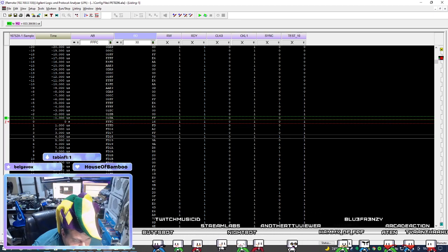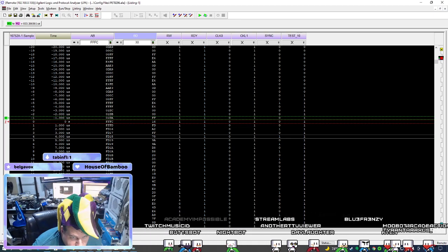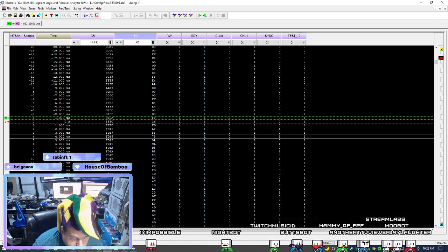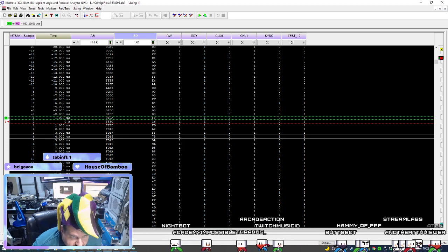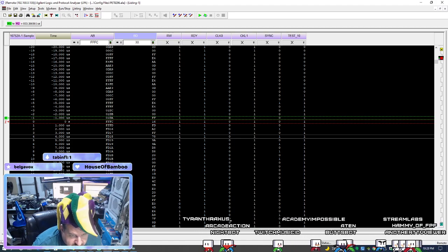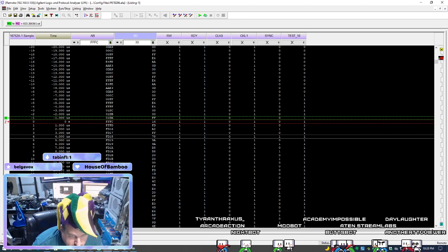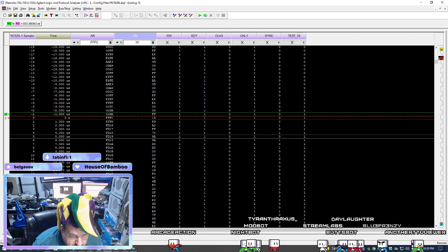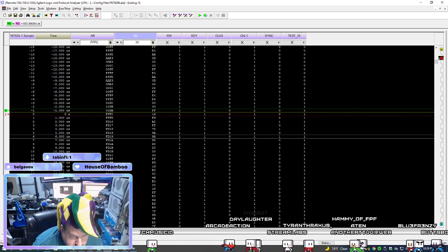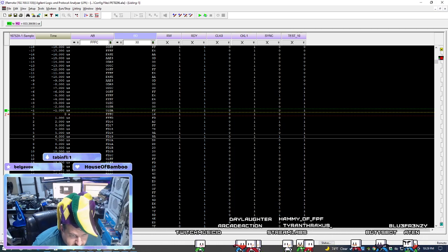So what we're going to do is just go through here and quickly look at this. This looks like a stack pointer. It looks like the stack is sitting at 1FFF. So this address 1FFF, FD1D, possibly. Not sure. Then we're going to jump to E000. So it looks like we're definitely running code at E000.